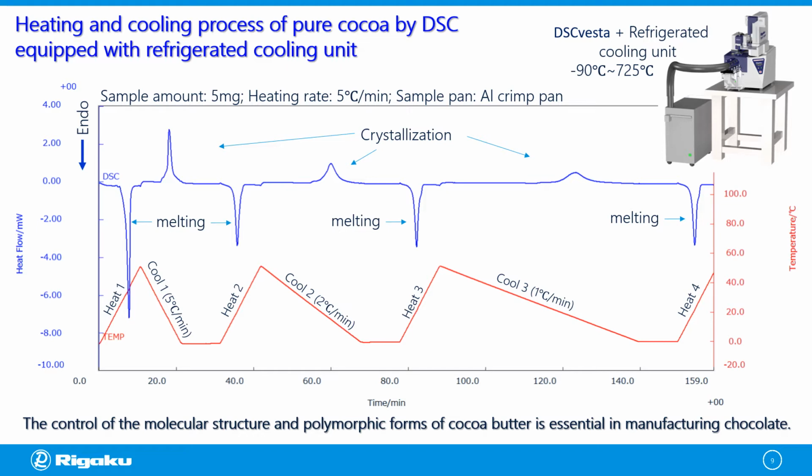In the first heating, we can observe that the melting behavior is sharper, revealing a different melting peak compared to the second, third, and fourth heating. This is due to the effect of thermal hysteresis of the sample. By performing melting on the sample, we are able to cancel the thermal hysteresis of the material. However, as we heat or cool, we are imposing a new set of thermal hysteresis on the material.